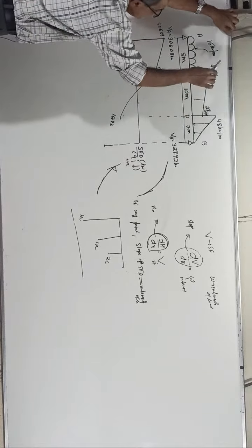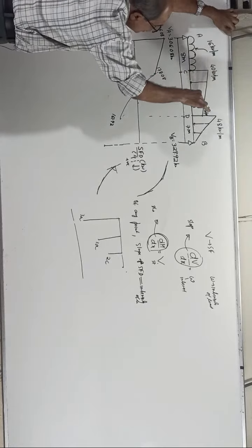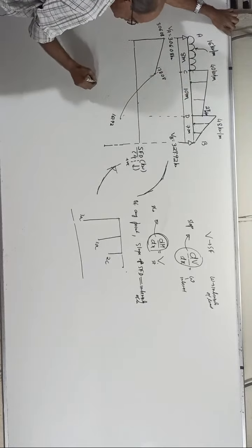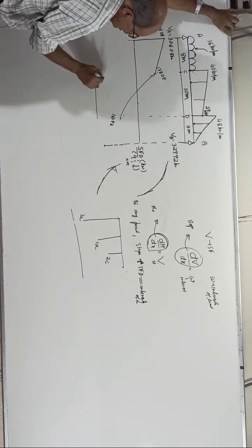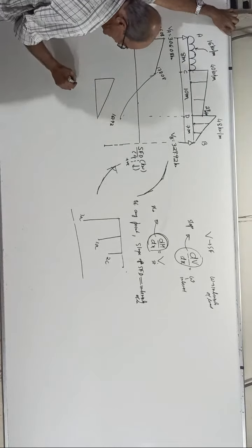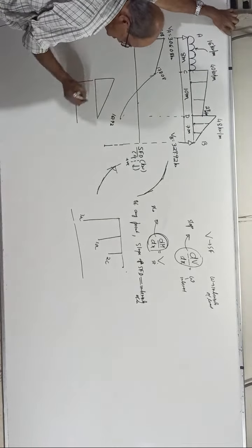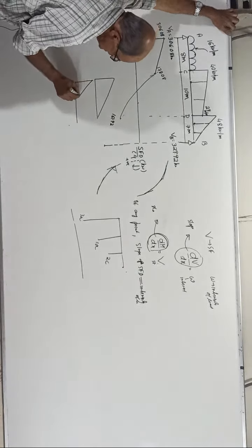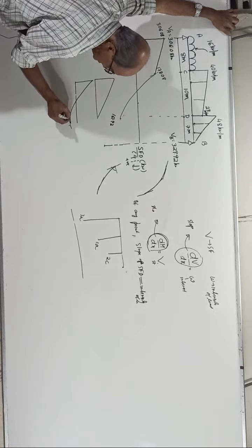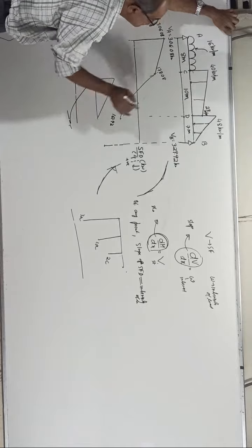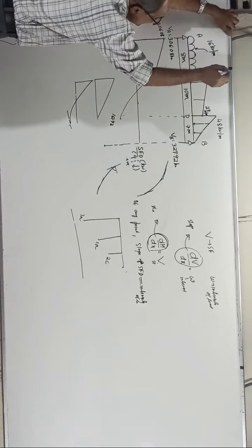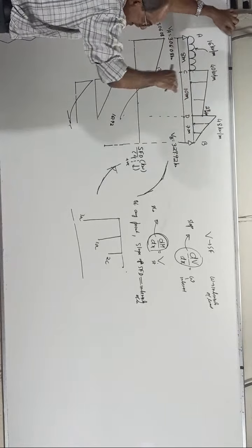Suppose, imagine, this is a uniformly varying load like this. See, one minute, see now. Suppose this is a uniformly varying load of this type, then when you come here, slope should be 0 here. Why? 0 intensity. But no, instead of 40, when you reach here, slope should reduce to 28.